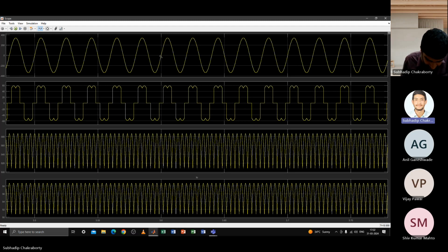I told you in the group also, right? The active power transfer for the harmonic components will be 0, considering voltage does not have any harmonic components. However, the reactive component is also 0 since there is no phase shift. So only the harmonic components of the currents need to be handled by the filter. So obviously the filter current will contain the harmonic current of the load, which we denote by ILH, the load harmonic current. That is the filter current rating.